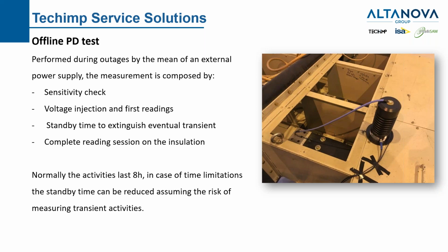Our acquisition unit doesn't have any problem with 2 nanofarad, 1 nanofarad capacitive couplers, or 80 picofarad as well. We can always take a measurement with all the different sensors and make a comparison of the generator insulation condition.